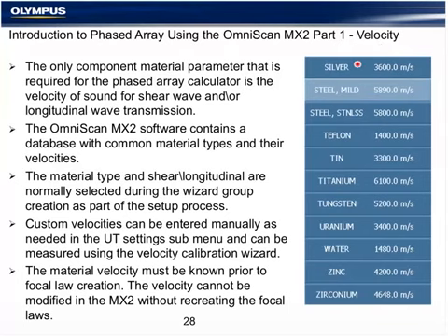Normally, for carbon steel weld inspection using normal P numbers and typical API typing, selection of the velocity from the database is just as accurate as your ability to measure it for the delta. There are several ways of measuring velocity. We'll talk about those in later sections. Normally, it's selected from the database.